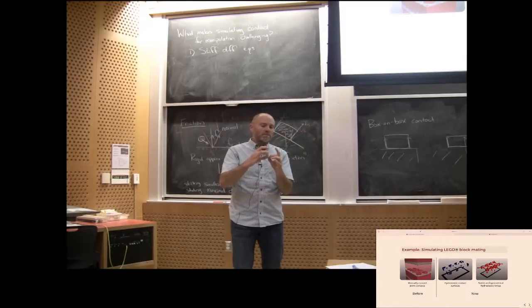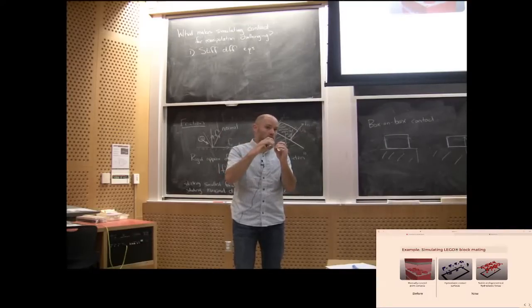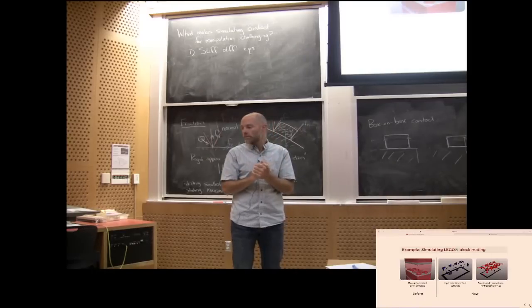So fundamentally, if we think about a spring model, then there's no contact force until penetration. So the first choice is to do that. The alternative to a spring model is to handle the impulsive forces and try to obey those constraints exactly. There is a mode where you can put one soft thing in with another hard object in hydroelastic that does some of this work. But right now, in the simplest version of the model, forces are only defined once you're in penetration. That's when you have a surface to work with.